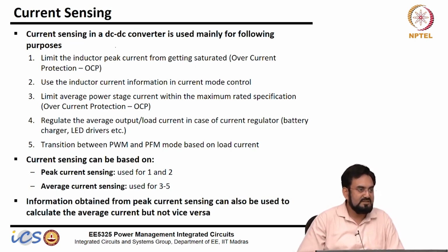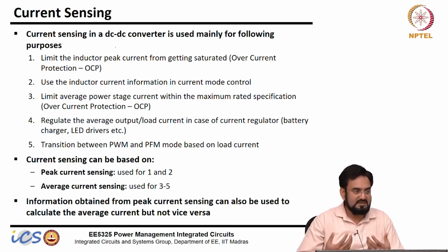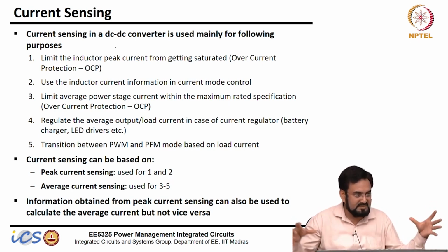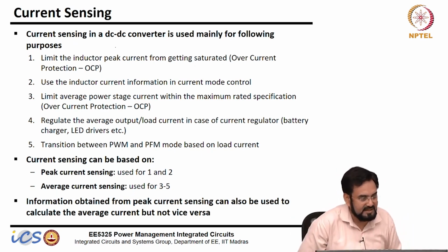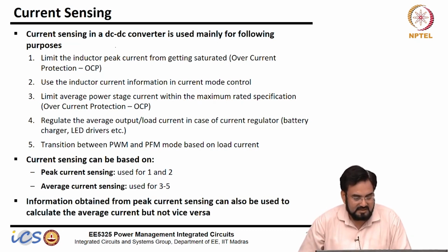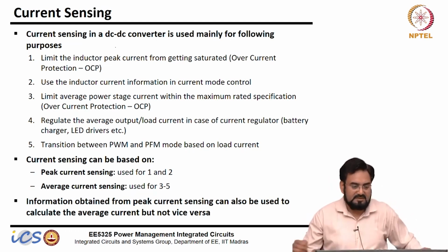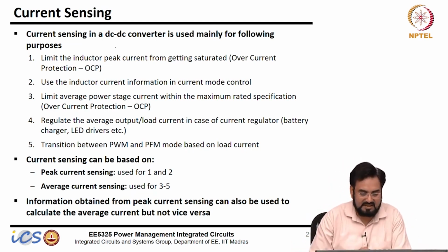The main reason is we want to protect our device from short circuit or when the load becomes very high. We want to protect MOSFETs, our routings, metal, everything, because they have a certain current rating, and the MOSFETs you have designed cannot cater more than the current you have designed for. So they will heat up and may melt, or your devices may break, anything might happen.